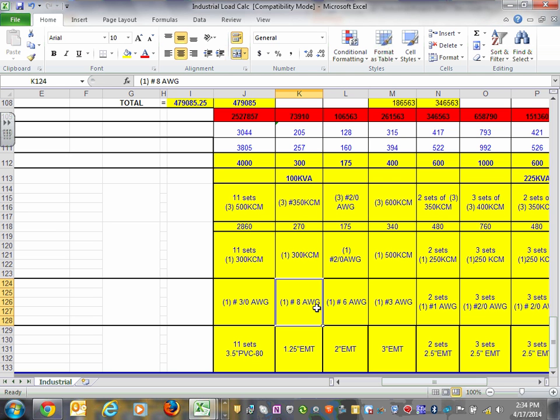Now, if you have an EMT conduit, a lot of us engineers like to pull extra. You don't depend on the EMT to ground you, especially at the panel, so you pull that conductor into it. So I have number 8, number 6, sized based on the overcurrent protection device. I'm assuming we're pulling a neutral even though we're using EMT conduits, which is an approved wiring method for a certain length.